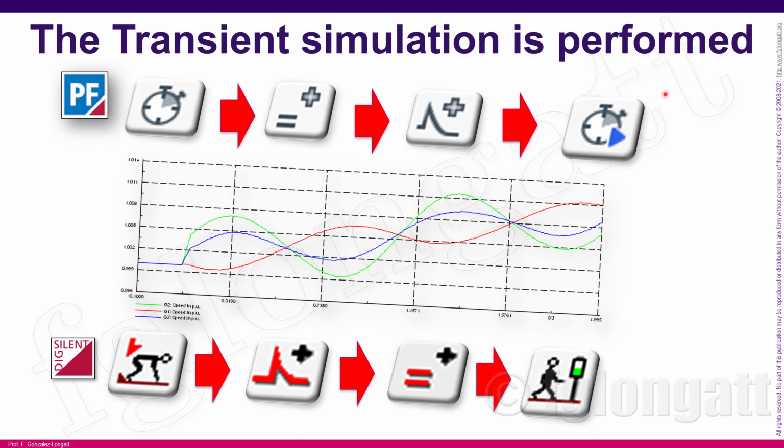Perfectly fine, okay? Finally, before we finish this presentation, it's time for a short summary. What you need to do is basically run initial conditions, then define the result variables, define events. You can swap this, okay? You can define the events and then the results is not a problem. The order is not affecting the result here. And the last step and the most exciting, press the button and run your simulation.